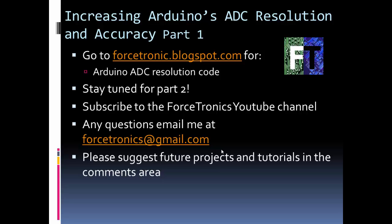You may not want to match your reference to a very small voltage level. What you probably would want to do there if you were trying to measure a very small voltage level is to use an amplifier such as an op amp, which is a whole other tutorial, but an op amp would be a way to go to boost that real low voltage sensor value up to a higher voltage and then measure it with your ADC.